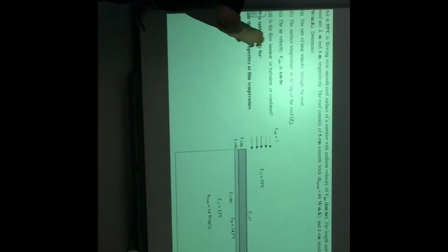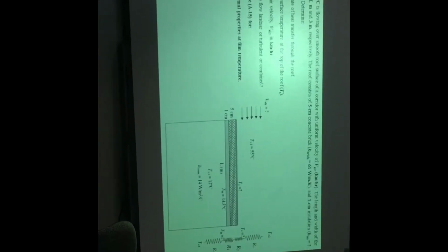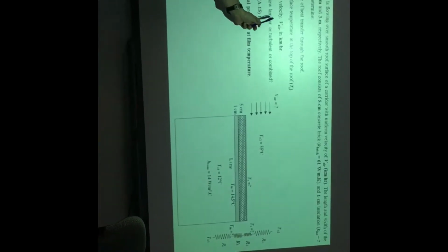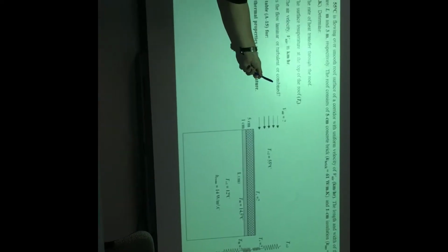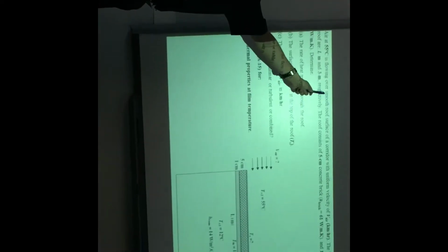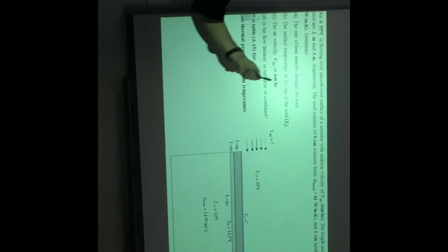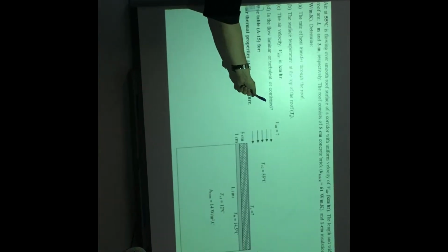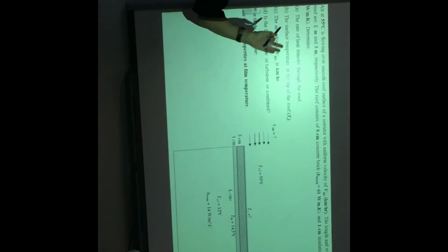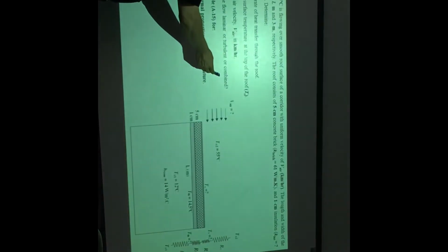You assumed laminar, but after you calculate the Reynolds number it becomes more than 500,000. It means your assumption is wrong. Your case is not laminar. It's either turbulent or combined. Because the surface is smooth, look. If it were rough, it would be turbulent from the beginning to the end. So your case is either laminar or combined.